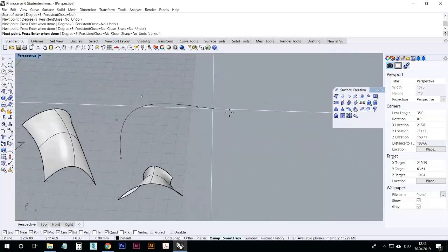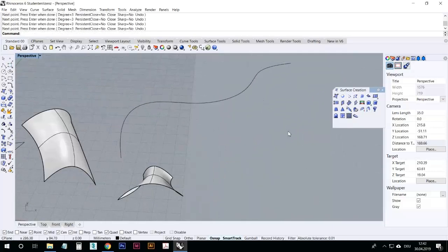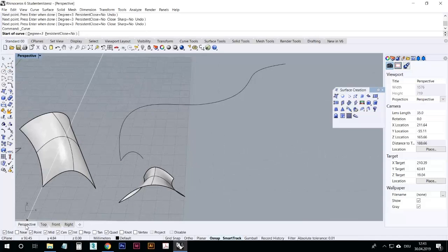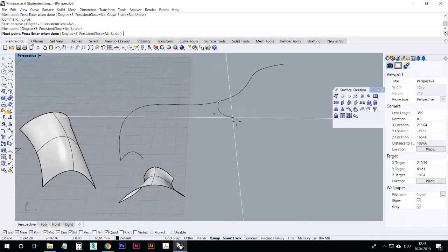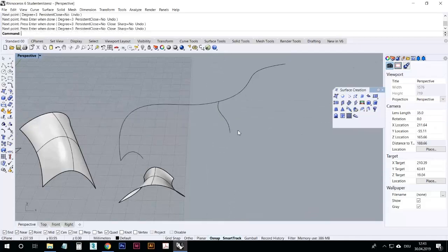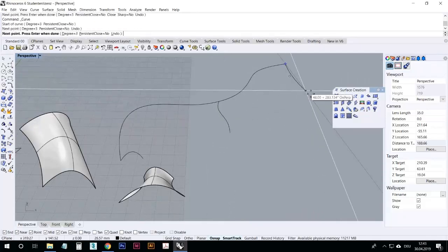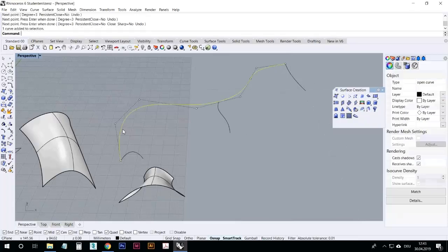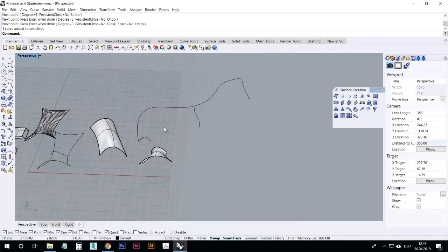Maybe you will have something like this. So that's what it's called, sweep rail. You know, it's almost like a rail, and then you have your section curves. Maybe you have a section curve like this, and here you have a different section curve. Now I pressed near to be able to snap on it wherever. Maybe a section curve looks like that. You know, in the end you have something like that. If you choose sweep, it would use this rail, build the curve along it, but get help from these section curves. So, well, this is going to be quite a weird surface, obviously.